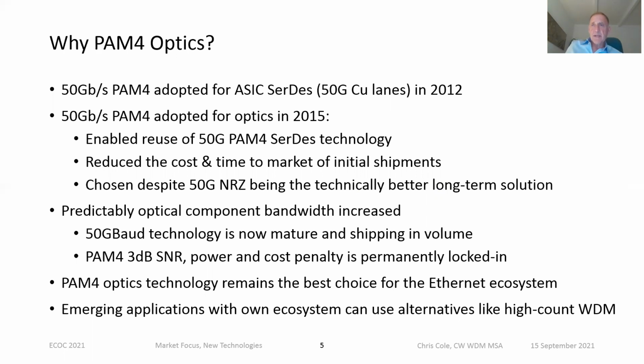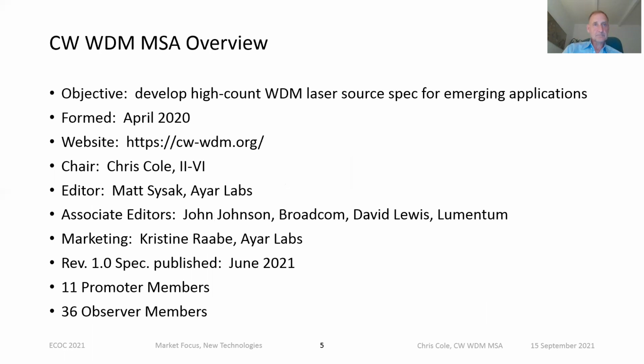However, emerging applications with their own ecosystem can consider alternatives like high count WDM. They're free to optimize their technical solutions. And this is where the CW-WDM MSA comes in. Its objective is to develop high count WDM laser source specs for emerging applications. Note that it does not include writing a link specification. That is left up to the users.